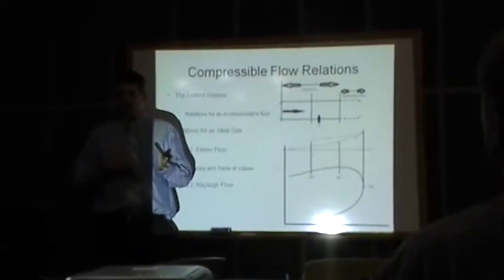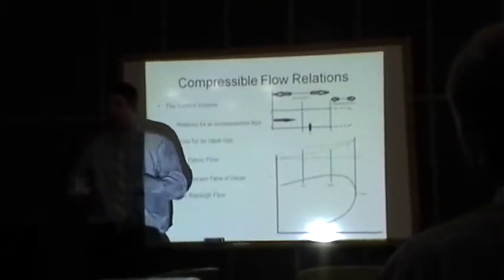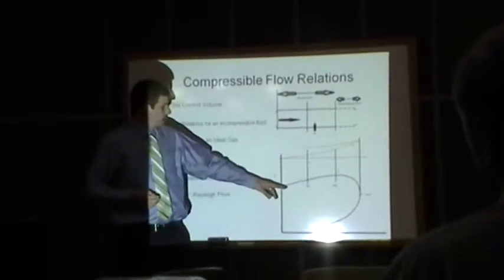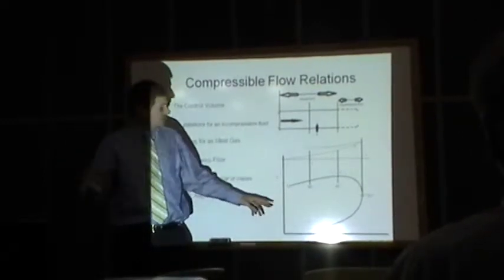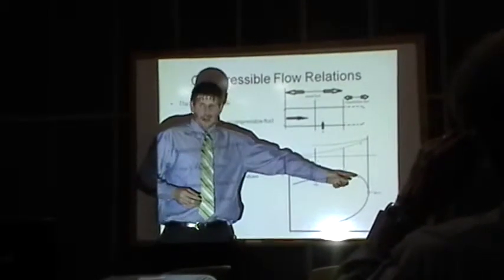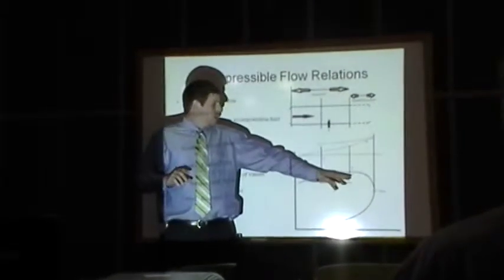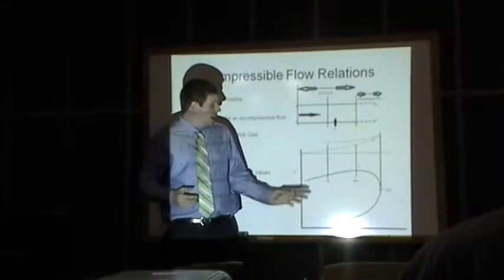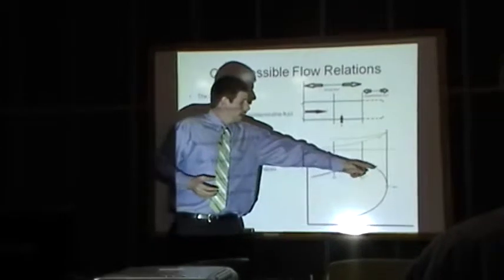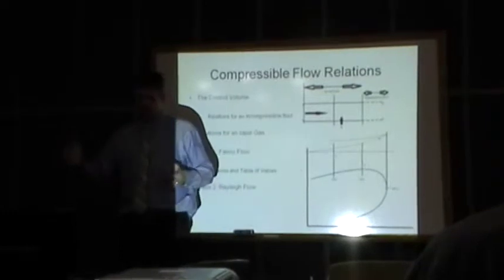And if we look at the energy of the system at one point compared to another point, if you add heat to it, we're assuming the energy is conserved, so we have to take that into account. Now, this does have some interesting influence on the static properties, because the temperature of the fluid will increase up to a certain point. At that point, any additional heat added to the fluid will not increase the temperature, it'll decrease the temperature slightly and just add to the overall energy of the fluid itself. So all that heat energy essentially gets converted into velocity that accelerates it to Mach 1.